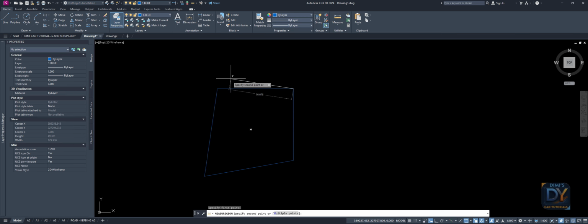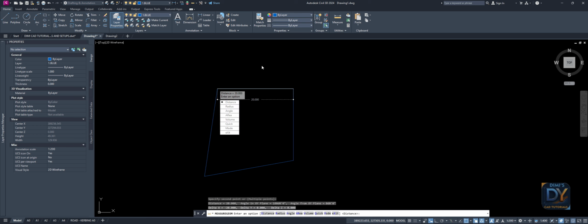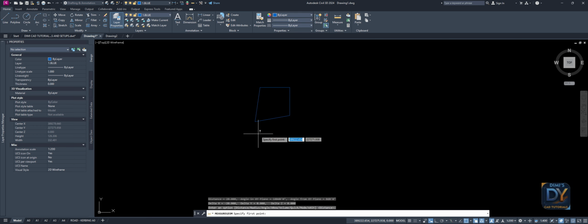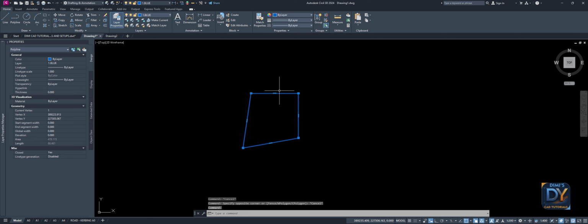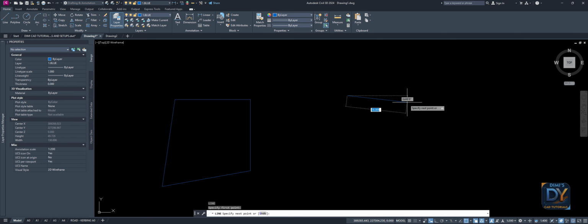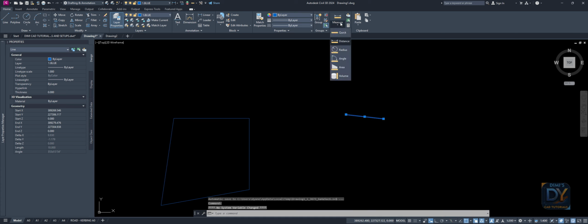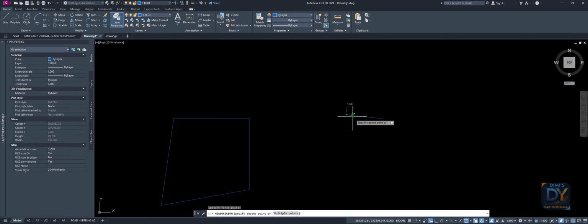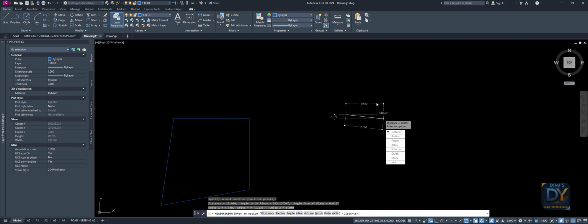You can use the distance measuring tool. You have to be careful with it. It works if we have a 3D distance somewhere. Let's say this one is a 3D line, for example. I draw a line which I'm going to call 10 meters. This is a 10 meters line. If I go to my measure distance tool and check, it says 10 meters.